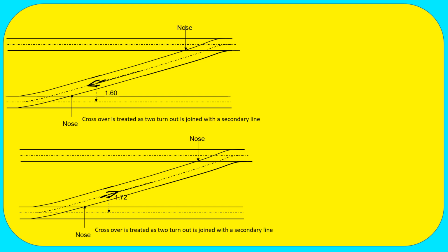So the runner is connected with the top main line OHE. So it is in another section, and the main line OHE pantograph will touch the other section. So here electrical clearance will be added. So here also you cannot reduce this distance less than 1.72 meter.